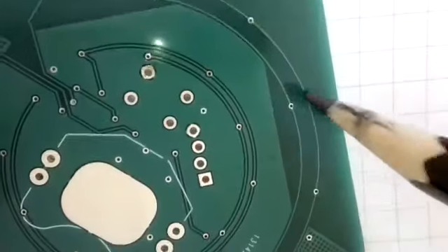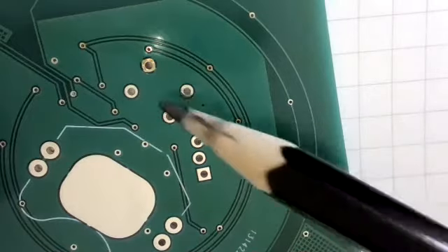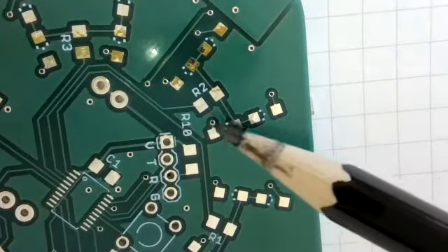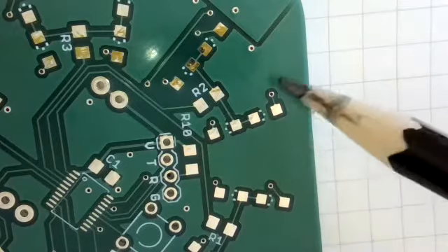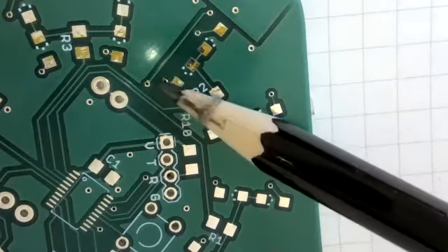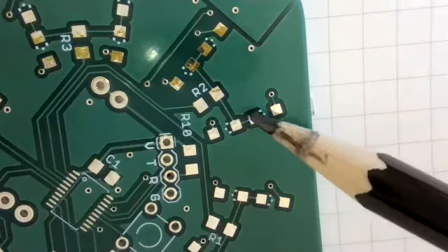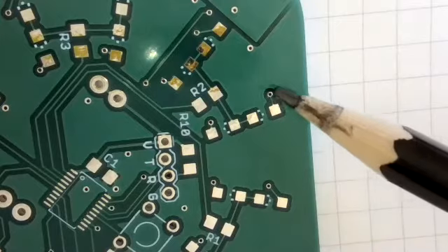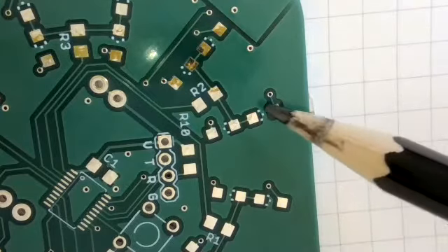All right, and so what we see here on the back is that all of those diodes are connected to these rings, and these rings come back and connect to the MSP430. The idea is that in order to have one of these diodes turned on, we have to turn on this line, and then we have to turn on one of these 1, 2, 3, 4 separate lines. So there's 6 banks of 4 diodes, and each bank can be controlled by turning on the resistor, and each diode can be turned on by turning on the particular pin, right?